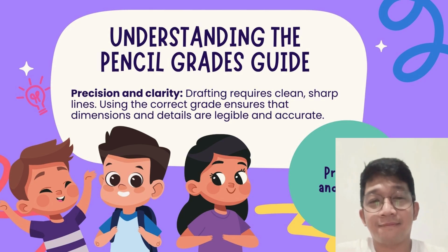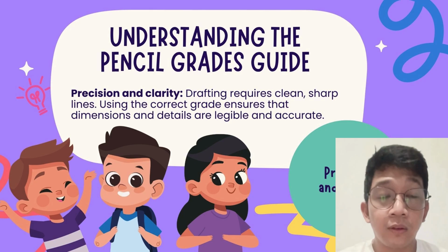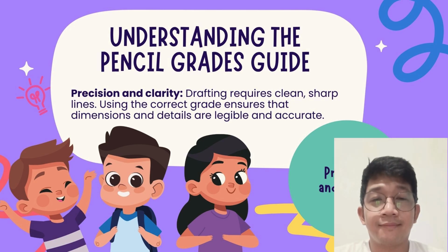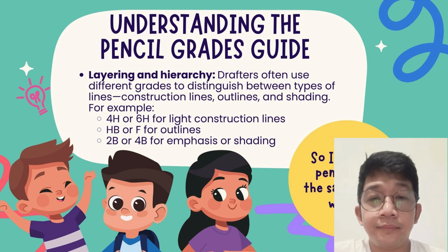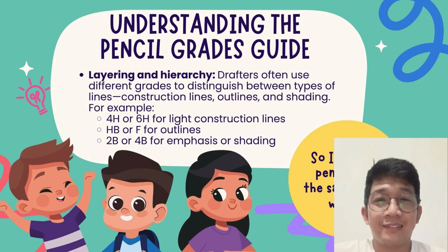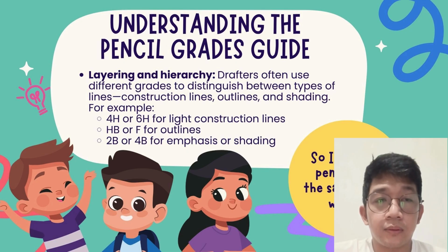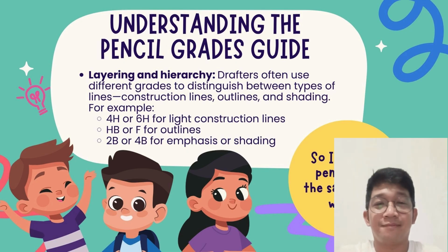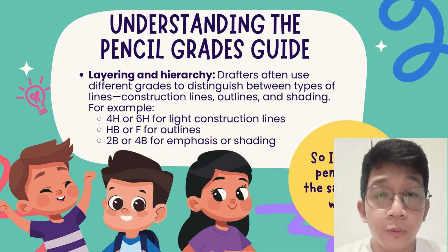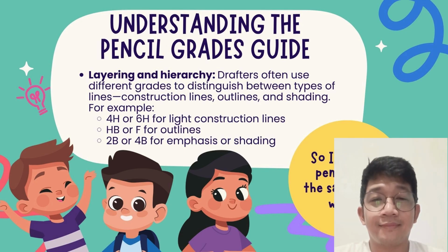Precision and clarity. Drafting requires clean, sharp lines. Using the correct grade ensures that dimensions and details are legible and accurate. Layering and hierarchy. Drafters often use different grades to distinguish between types of lines: construction lines, outlines, and shading. For example, 4H or 6H for light construction lines, HB or F for outlines, 2B or 4B for emphasis or shading.